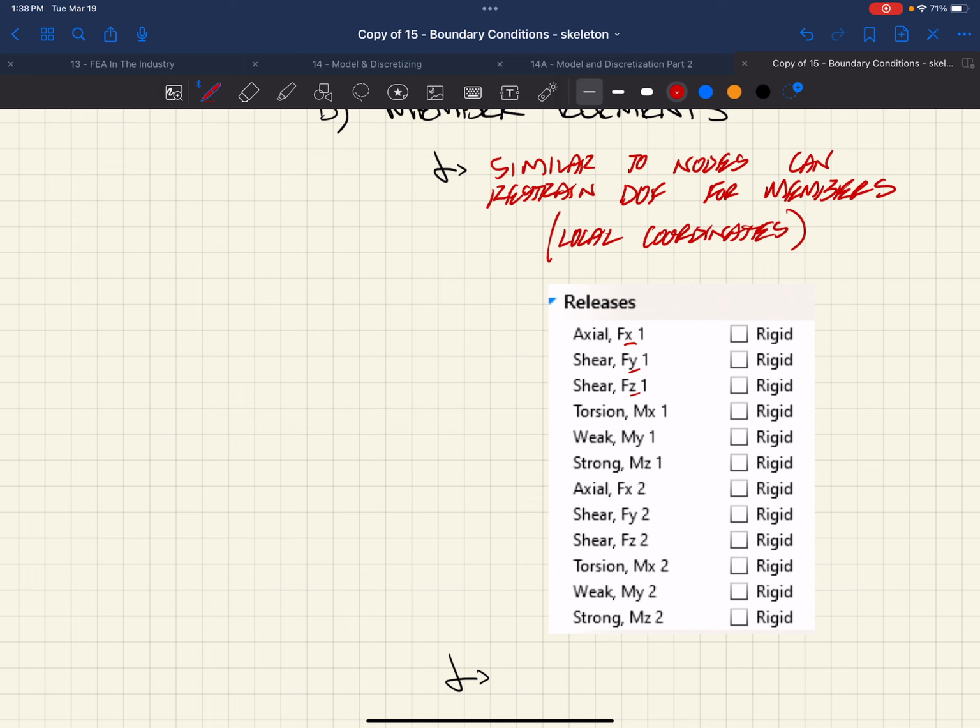Axial forces, shears, but they can also give you global force moments, right? That are applied at a given location in the member, or model. And so you need to be careful that when you go out to get your results, you're pulling the results that you know are acting at a specific location and in a specific direction. And you can then relate that back to a specific strength, right?